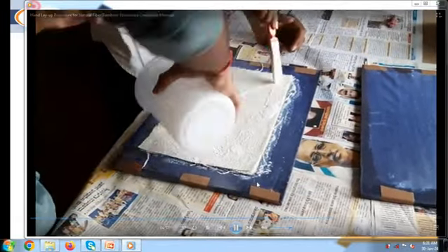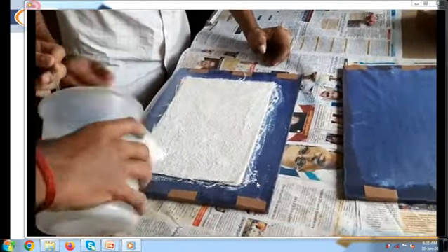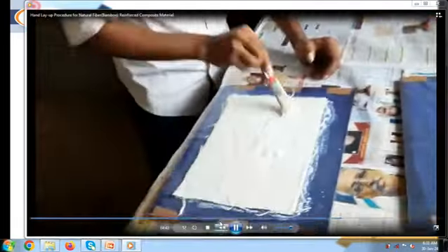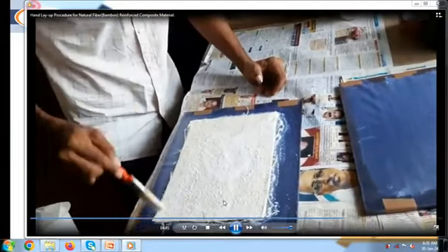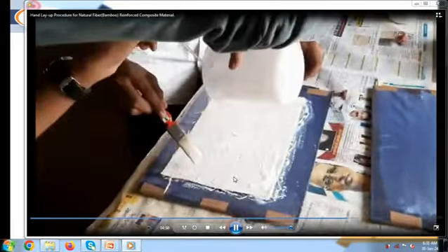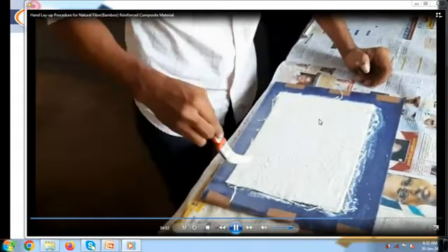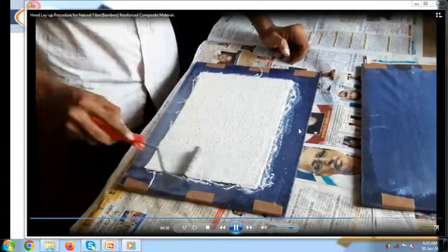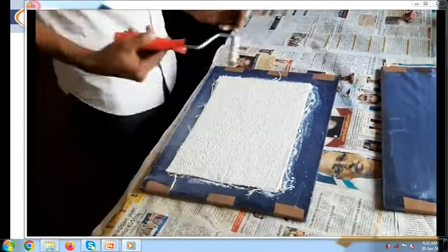So you have to use the brush as well as the roller, so that all the resin is properly worked into these fibers. The filler material will go into the void spaces already there in the fibers, so that it provides proper strength to the fiber.